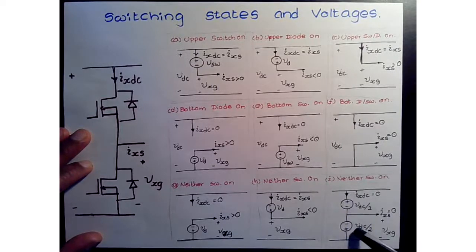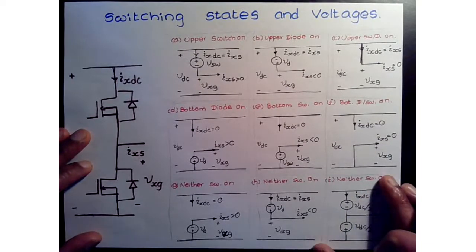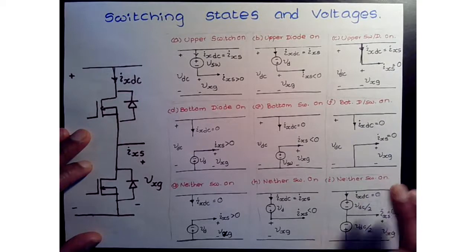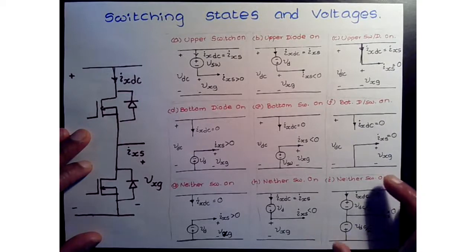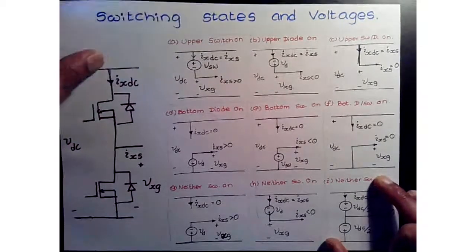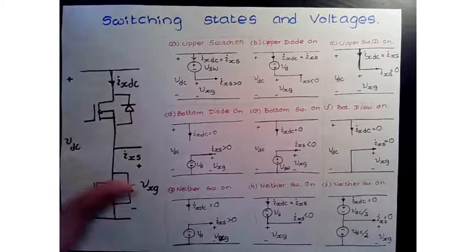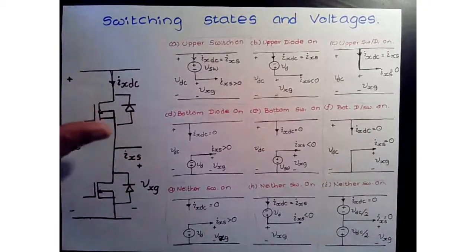So we typically assume that the voltage of the DC bus is equally split, and this condition doesn't occur very often. But just in general, we have that condition in case we need to model a certain phenomenon. Okay, so these are the three different combinations you'll see for any switch in this three-phase inverter system.